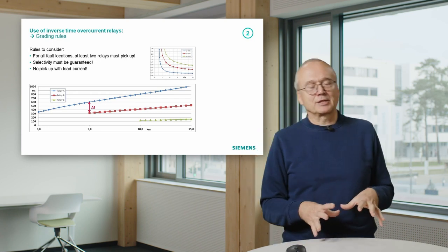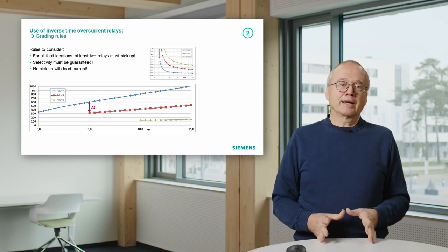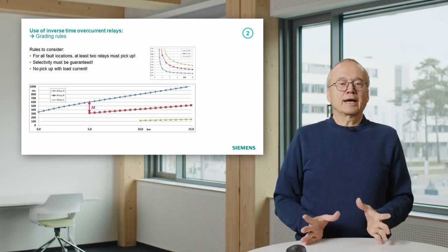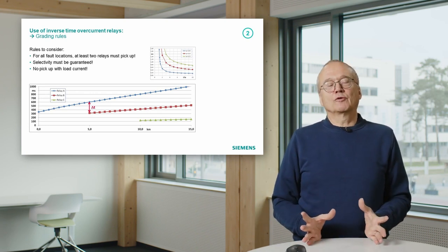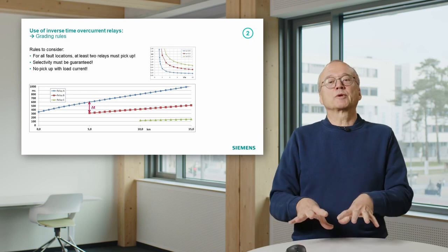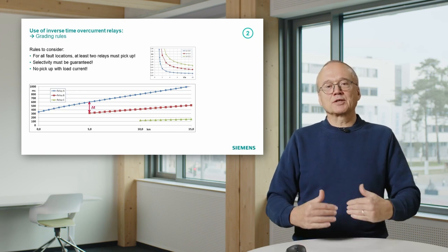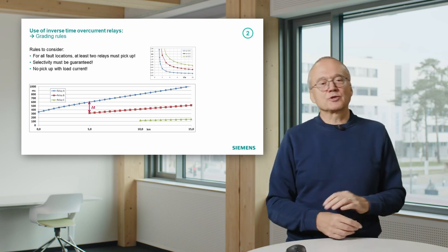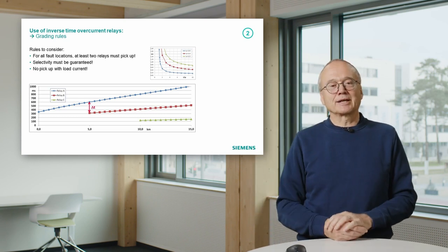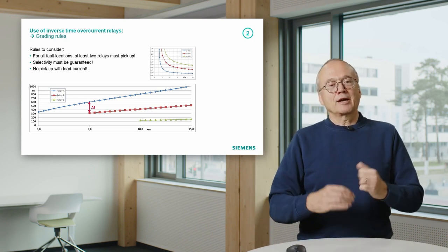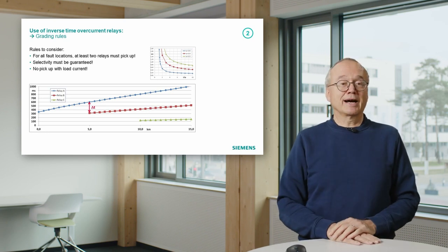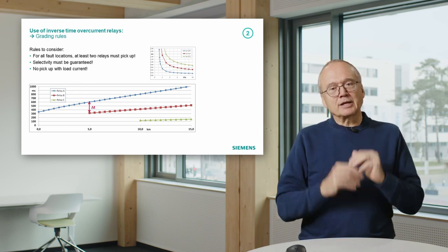Remember, I discussed that example in one of the first videos, where you had a blackout of a part of a city which had been without energy for some hours. If you re-energize that, maybe a lot of aircons will be starting, which have a pretty high current, and your setting should be high enough to avoid tripping with that current. And you can imagine